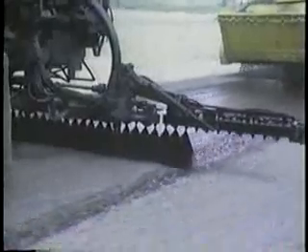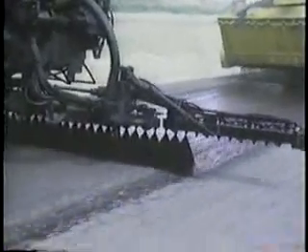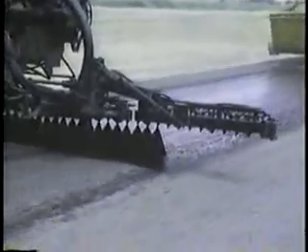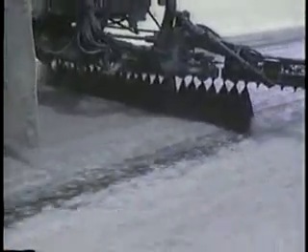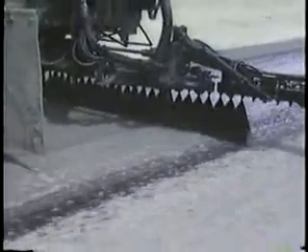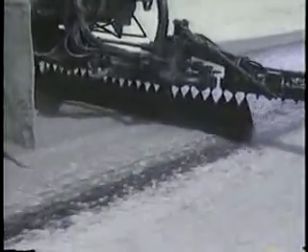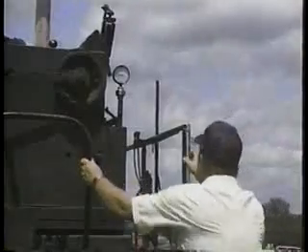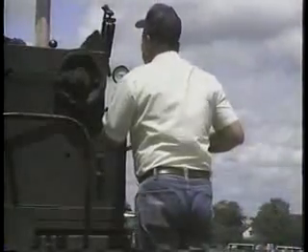Spray bar height also affects proper coverage. By adjusting both the bar height and the nozzles, different spray patterns can be made as shown here. Usually a double or triple lap is used for seal coats. The distributor's application pressure is also important to proper coverage.